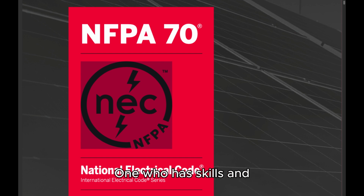Qualified person. One who has skills and knowledge related to the construction and operation of the electrical equipment and installations, and has received safety training to recognize and avoid the hazards involved. CMP1 Informational Note: Refer to NFPA 70E-2012, Standard for Electrical Safety in the Workplace, for electrical safety training requirements. Raceway. An enclosed channel designed expressly for holding wires, cables, or busbars, with additional functions as permitted in this Code. CMP8 Informational Note: A raceway is identified within specific article definitions.